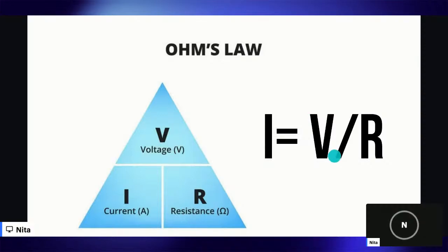Can you picture it? Voltage stays the same. Voltage increases. So more pressure, more push, but resistance stays the same. That would equal more current. If resistance increases, but voltage stays the same, then we would have less current flowing. If you lower voltage or increase the resistance too much, you may not have any current at all flowing.